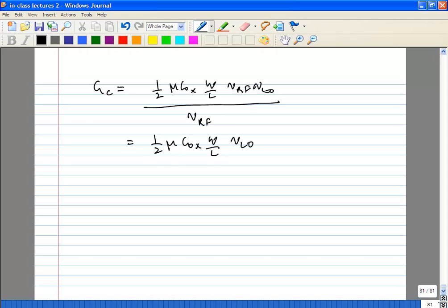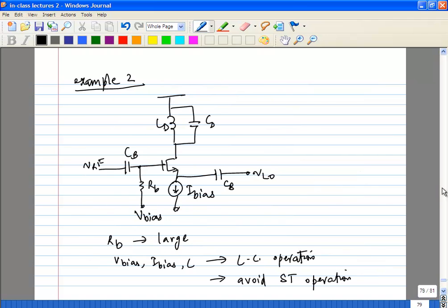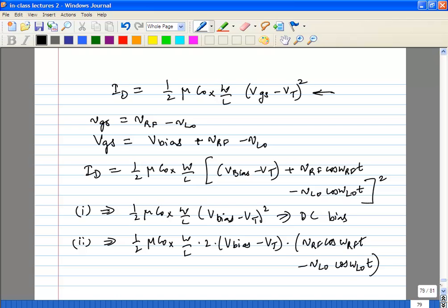What do we know about this term? This is actually the C2. Remember where we calculated for a square law mixer, it's supposed to be C2 times VLO. And remember that the characteristic of the mixer is basically just a square. It doesn't have C1V, it just has C2V squared. So if you compare this to the original C1Vn plus C2Vn squared, naturally this portion is C2. So it looks good.